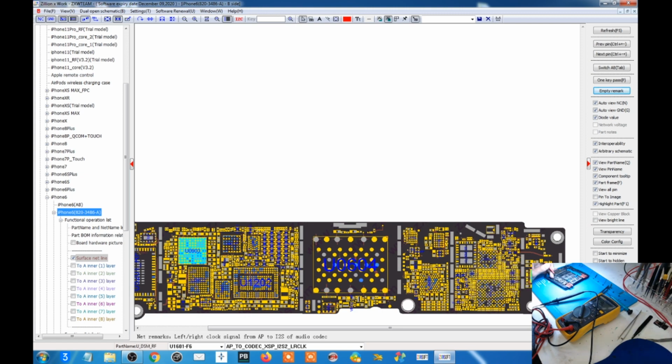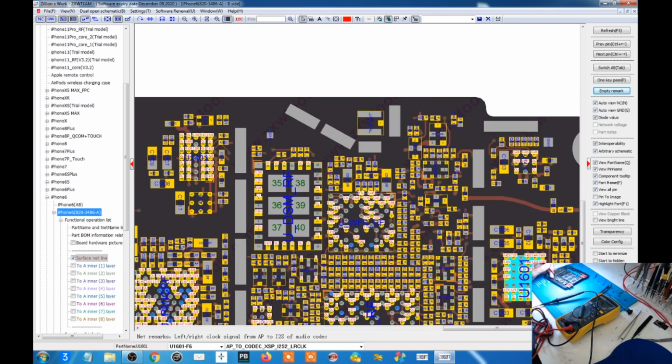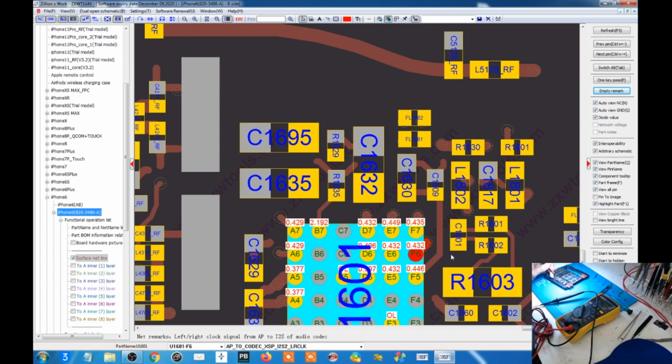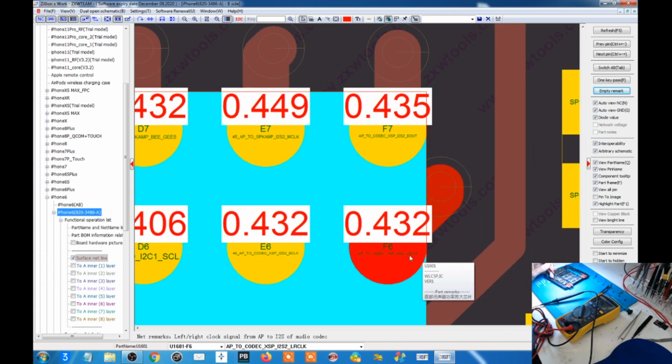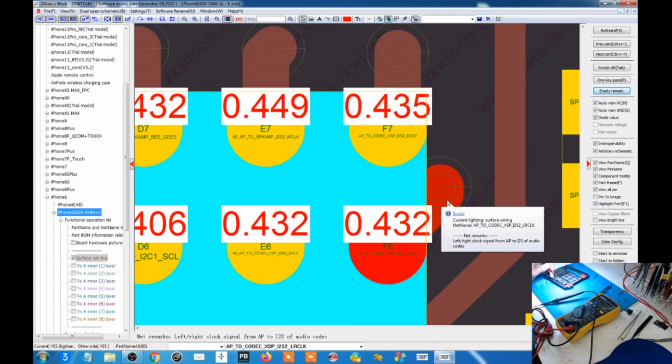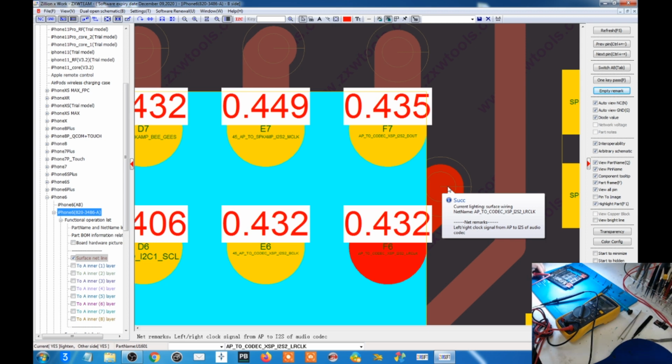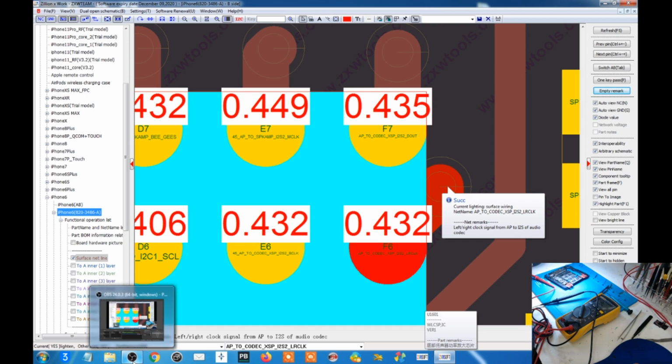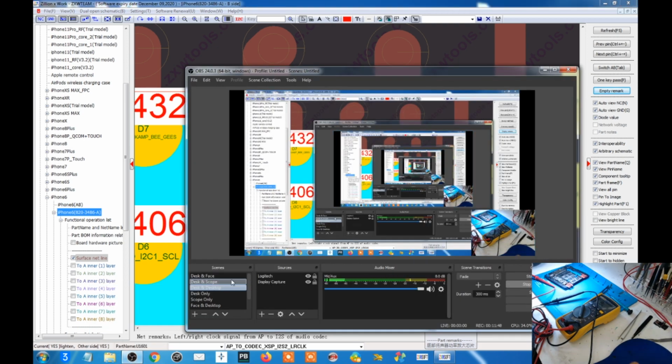So how are we gonna check? The first thing I need to check is the pad which is just next to this one. So maybe just this thing is broken, but the supply is coming up to this point on the side. So I need to zoom in and scratch that part and measure the voltage.